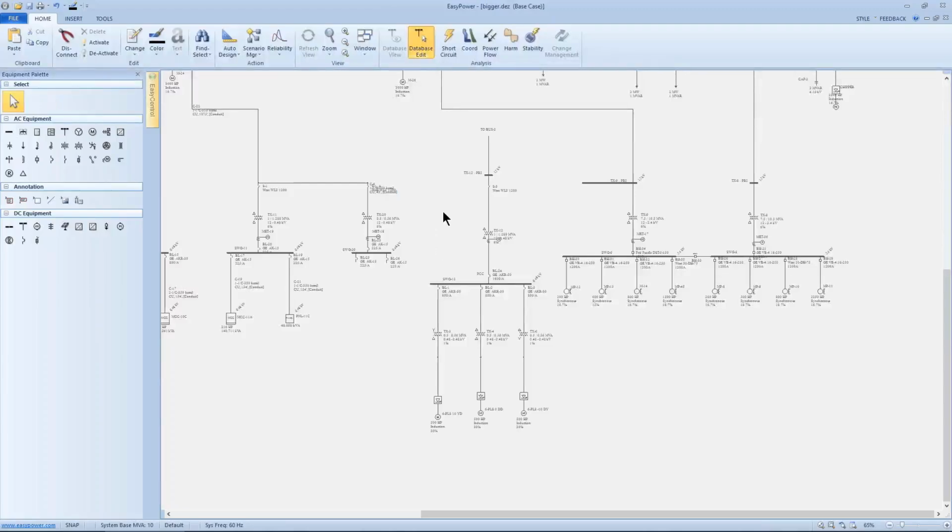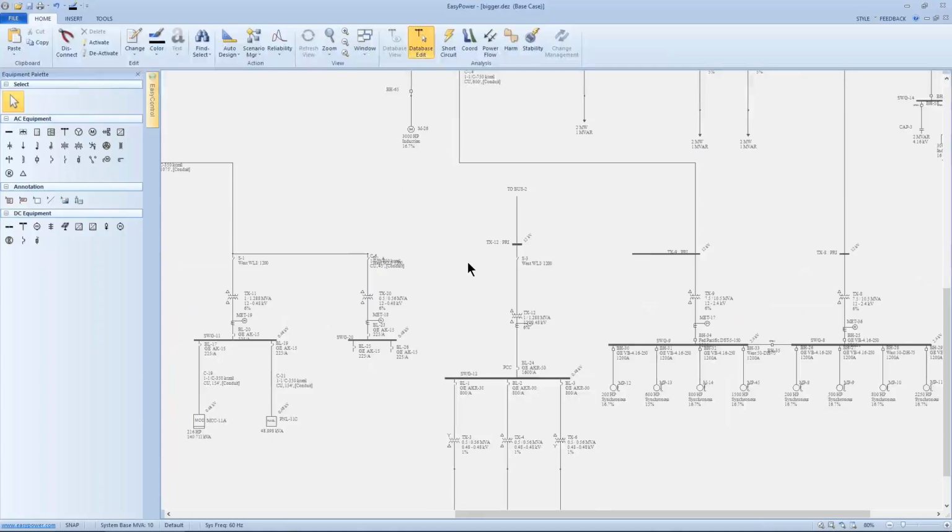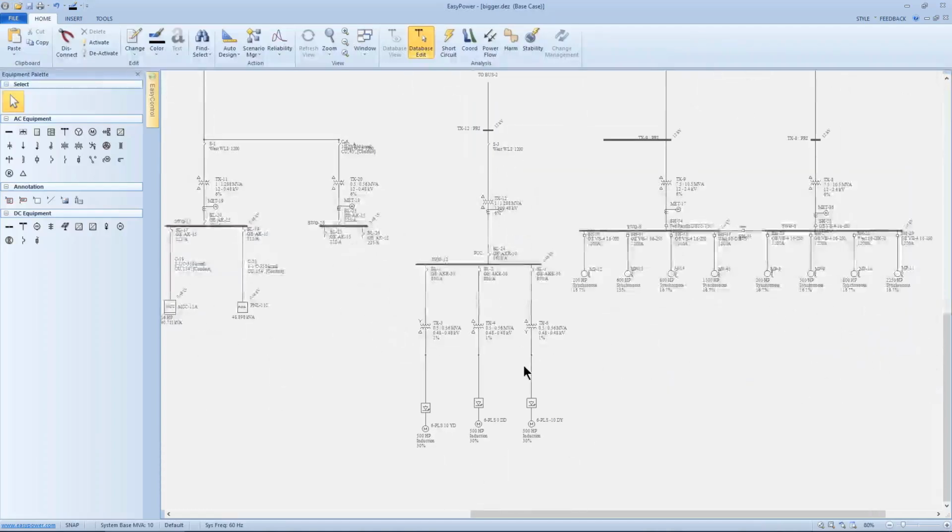But things like overheating transformers, a high current in a single leg that's not necessarily a ground fault, and especially if you have a high concentration of non-linear loads or drivers that have been introduced new to the system, are reasons to be considering harmonics as a possible solution to the problem.